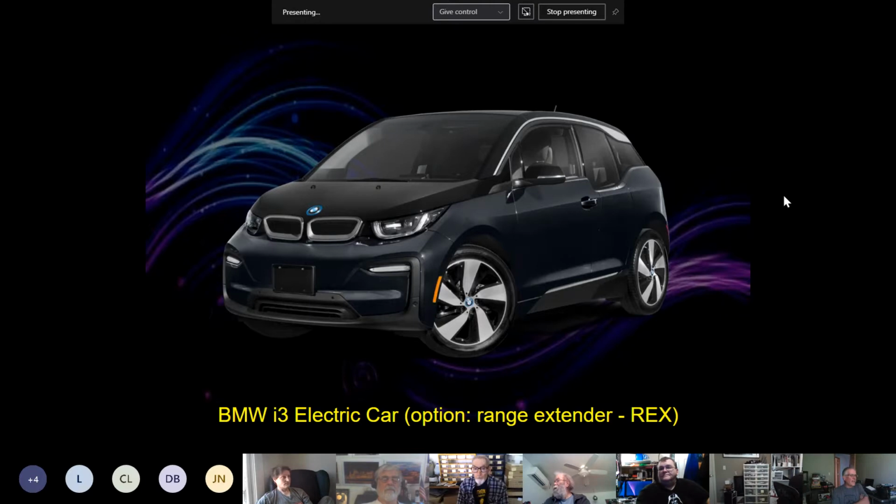And I mean, a quick charger. We haven't talked about those yet, but this particular guy uses the CCS standard, CCS1, I believe, quick charge standard, which can do probably 50 kilowatts. And the battery, oh geez, what size is this? I think it's a relatively small battery in this thing. I'm thinking it's 42 kilowatt-hours or something like that. So you can quick charge this guy pretty much from empty to full in well under an hour.